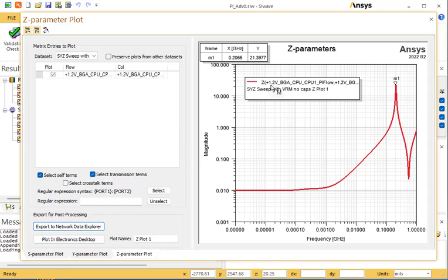And that's on the power plane 1.2 volt. We would like to extend our Z bandwidth beyond this value. So how are we going to do that? By adding decoupling caps. But where and what value and how many? The resonant mode solver will only answer the first question: where to put the decoupling caps.